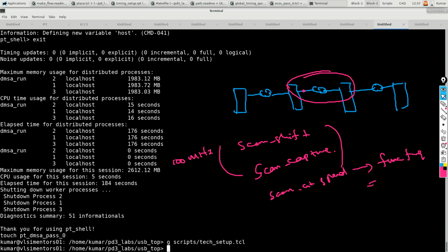See, if you get the pin placement from the top level, then you need to work with your top level and ask for a better pin placement. Okay, that is one method. Now, if you have created it, then you can actually move. Make sure you snap the pins on track. There are certain settings that you need to enable before you place the pins, or at the time of placing the pins you need to enable snap to track or something like that, and then place it.